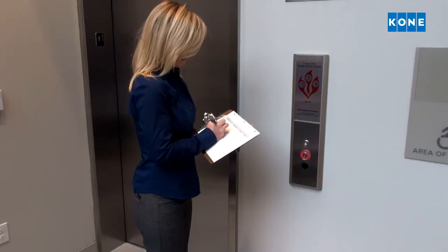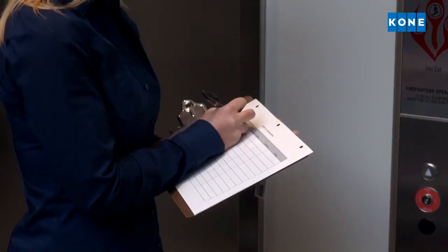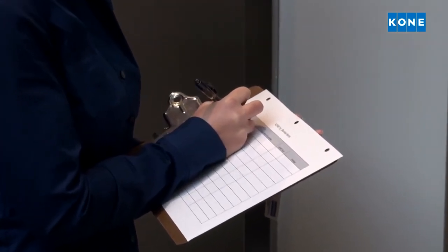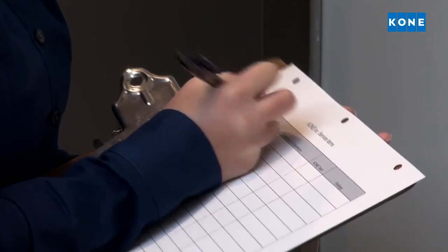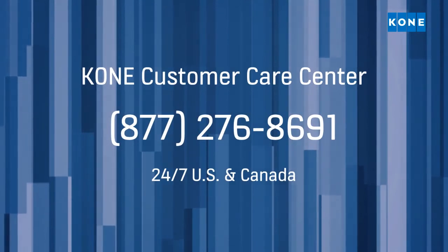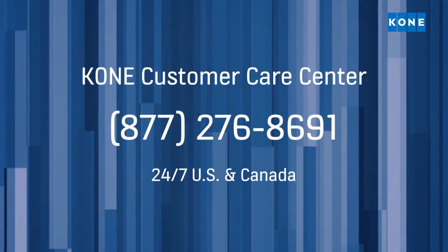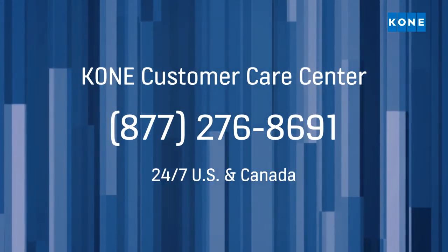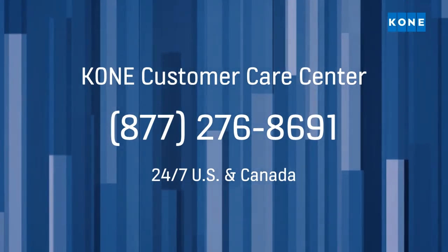By code, an owner is required to verify the Phase 1 fire service function of each of their elevators on a monthly basis to ensure they are in proper working order. An owner should record these checks on a monthly log for each elevator, which KONE has provided within your turnover documents. During these checks, if it is identified that the Fire Service Phase 1 function is not working properly on any of your elevators, or any indicator lights are not working properly, you should promptly contact the KONE Customer Care Center to request service of your elevator.